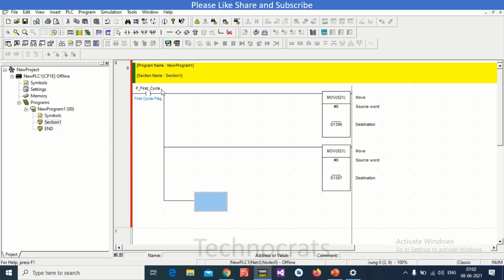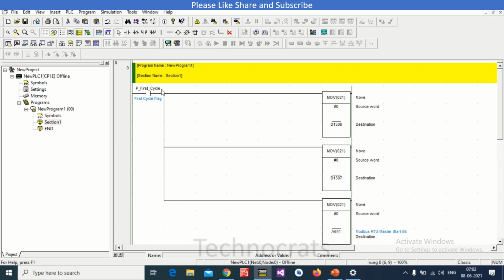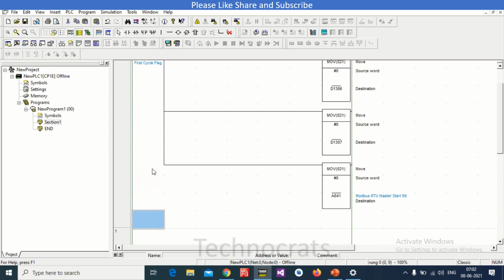Now we will write MOV #0 to A641. Okay, this is your Modbus RTU master start bit. Now the start bit is your A641.0. Now once the initialization is over, we will move to the programming section.